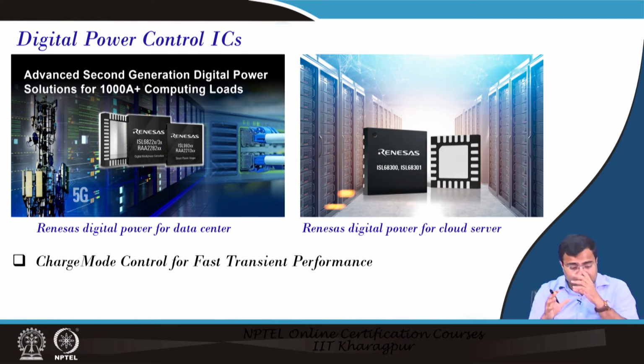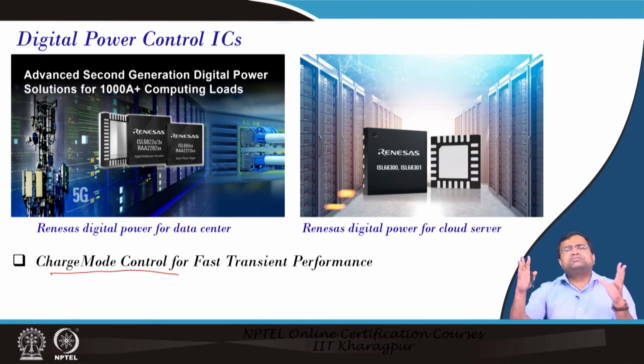Now, for this particular IC, what is written in the data sheet is that it uses a charge mode control, because when you go to digital, it is not necessary that whatever analog control we have designed, let us say for small signal based design, digital will be some Z domain of the small signal. No. Digital control offers you more flexibility to implement nonlinear control, and this IC uses something like charge mode control for very fast transient response.